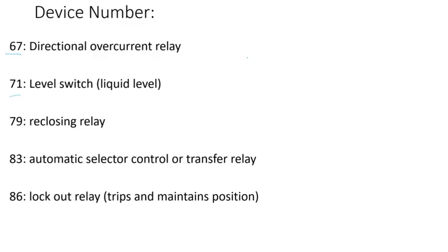Again, if I go back to that transformer sketch, you have a transformer tank, and under normal conditions, the oil, for instance, is at this level. So the liquid level gauge would be somewhere here, and it has a float. As oil gets warmer and warmer, it rises. So say it moves to this level.